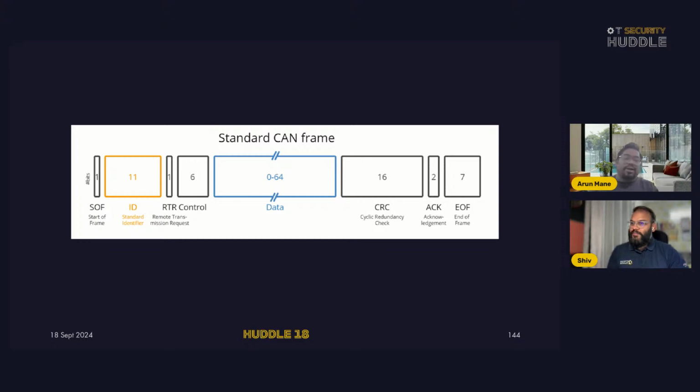So if I compare with the CAN bus, it is again clear text, and it's a bus. So if you are on the bus, or rather in the vehicle network, between two ECUs, you can intercept communication easily. That is the nature of CAN bus communication.